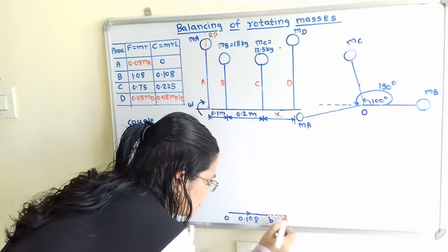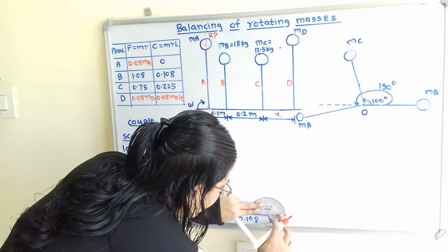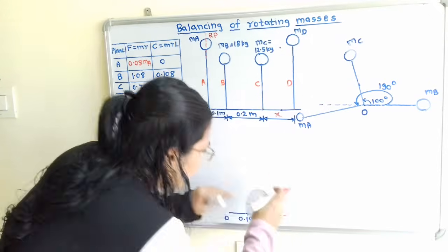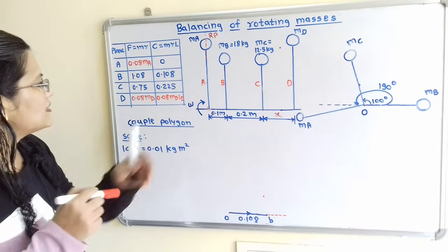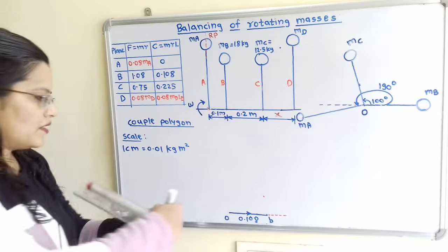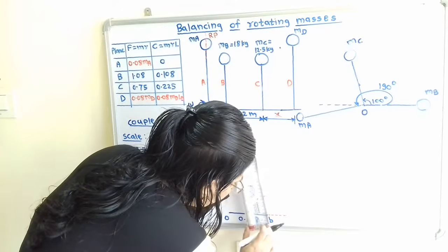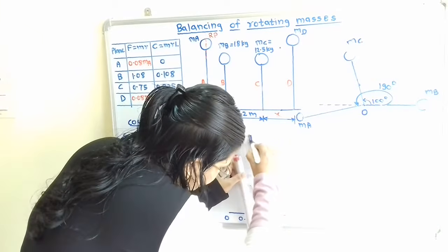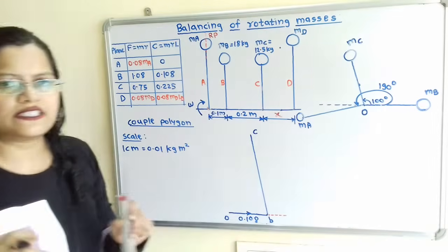And now from this reference line, select one point at an angle of 100 degree. So here is the 100 degree mark. Draw the line passing through that, and the length is 22.5 centimeter. And here is the next point, that is point C.